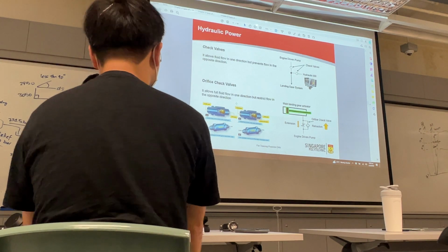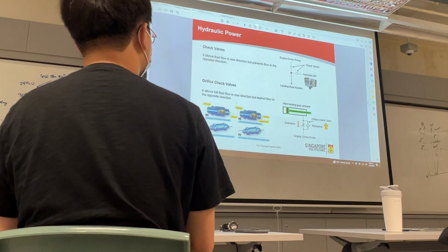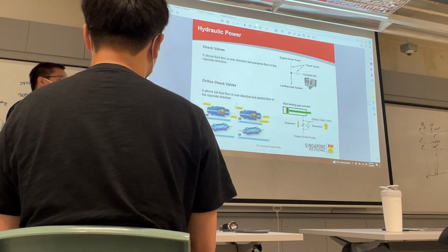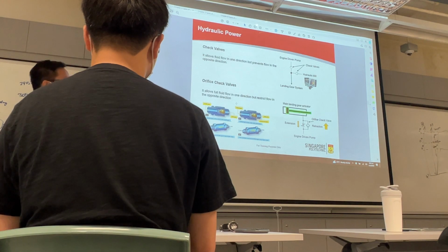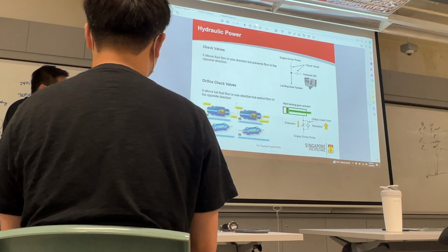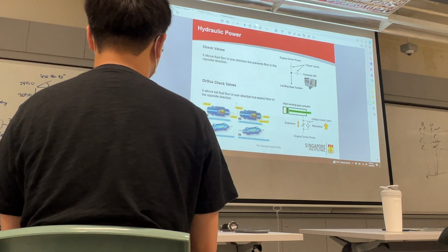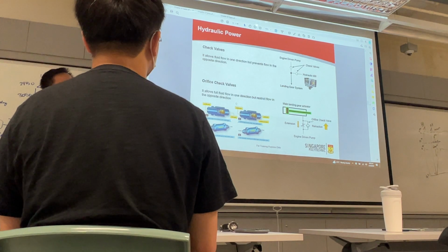Now for landing gear, when you just take off, you select landing gear up, right? The landing gear starts to retract. Do you need full fluid force? You need, right? 100, right? So that means for retraction, I need the orifice check valve to be orientated such that 100 of you go to the retract actuator to pull the gear up. Right? But how about extension?